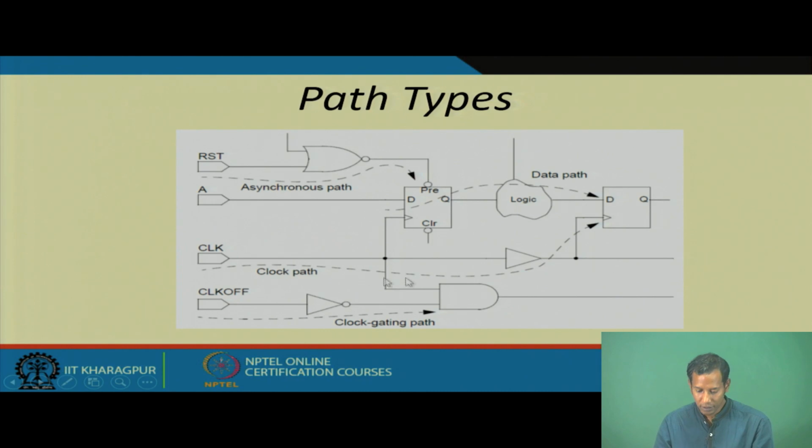So, mainly this is for a low power technique. Suppose I design this particular circuit, and the clock is free running, that means it is continuously running. In some cases, suppose the A value is 0 and it is not changing its value, that means A is fixed to let us say 0 or 1. Now, the clock is continuously running. Though this data is not changing its value, it is in the idle state. Because of this clock running, the whole circuit will run continuously, and if I run the circuit continuously, it will consume power.